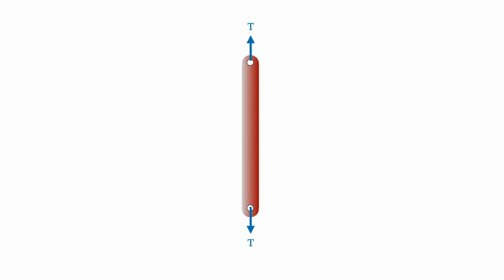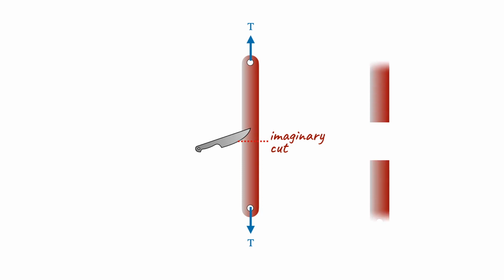So, using the method of section, imagine like you are cutting the middle section of the member. If it is being cut, then the single member will be separated into two separate features, which exposes the internal force occurring within the truss member. The internal force, which is drawn in the red coloured line, should comply to the equilibrium condition of the structure. Dalam erti kata lain, if at one end of the member it is pointed upward, then the internal structure will point downward macam tu. It should be in a balanced condition or in an equilibrium condition.